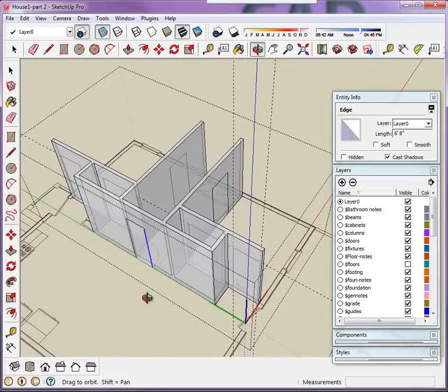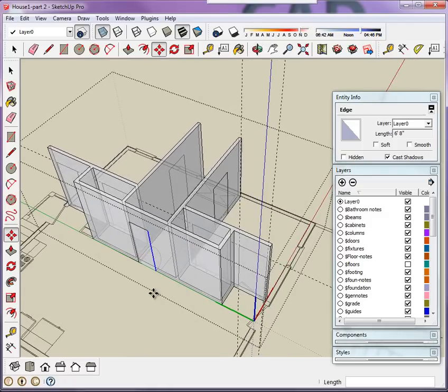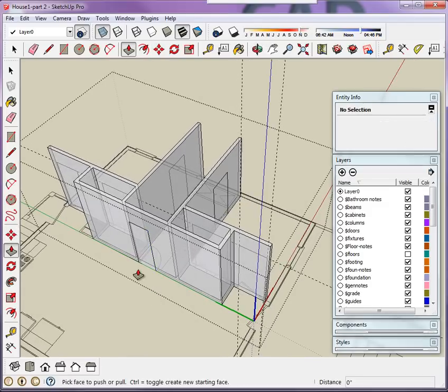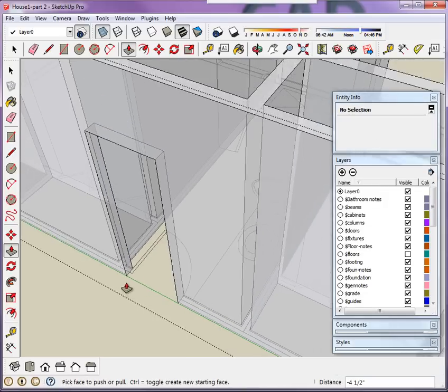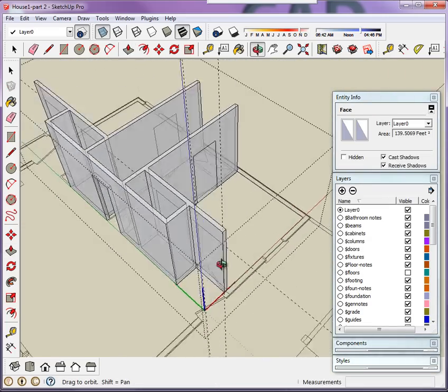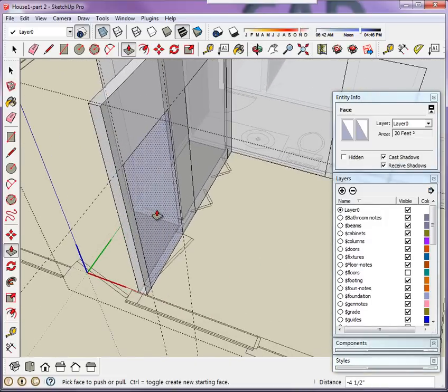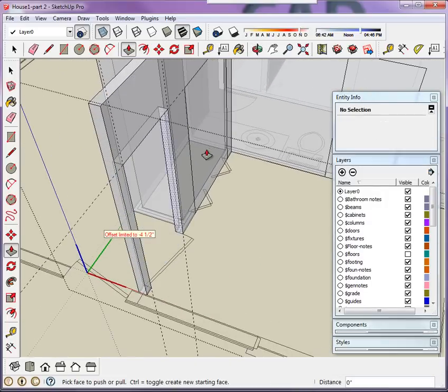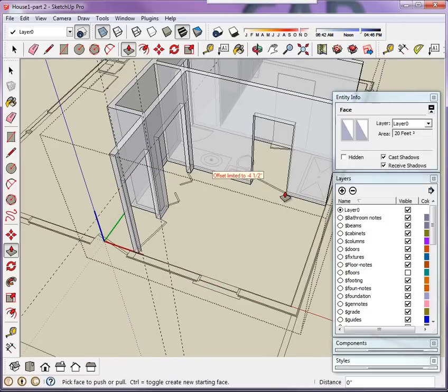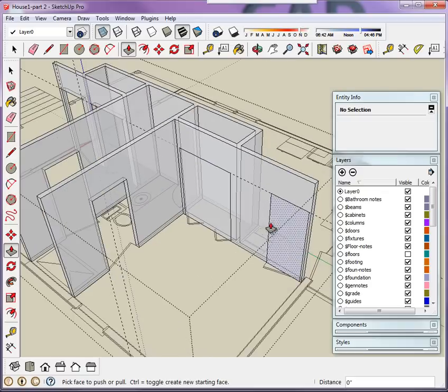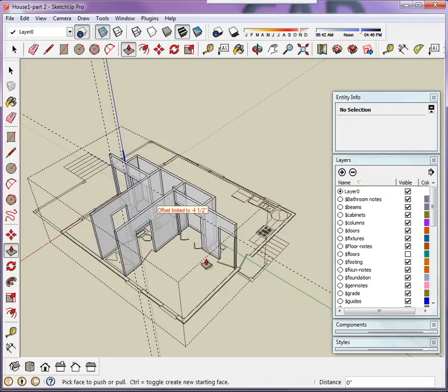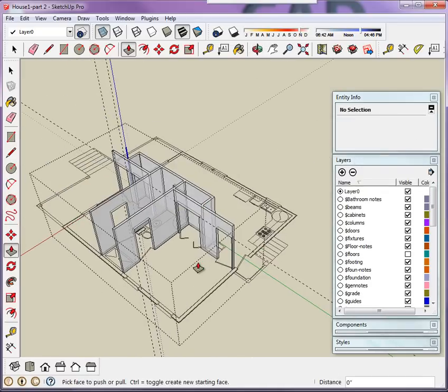So, once again, we're in the interior. All the wall thicknesses here are consistent. So, if I just go to push-pull, we'll do one. Start on the face, push through, look for the offset limit, or look for the opposite face. Should give you an opening. Now, we come over here, make sure you click on the correct face. Here you can see, right? And double click, there's your opening. Double click again, there's the opening, turn around, double click, and then you could double click these two. Okay? Now we're ready to insert the doors.